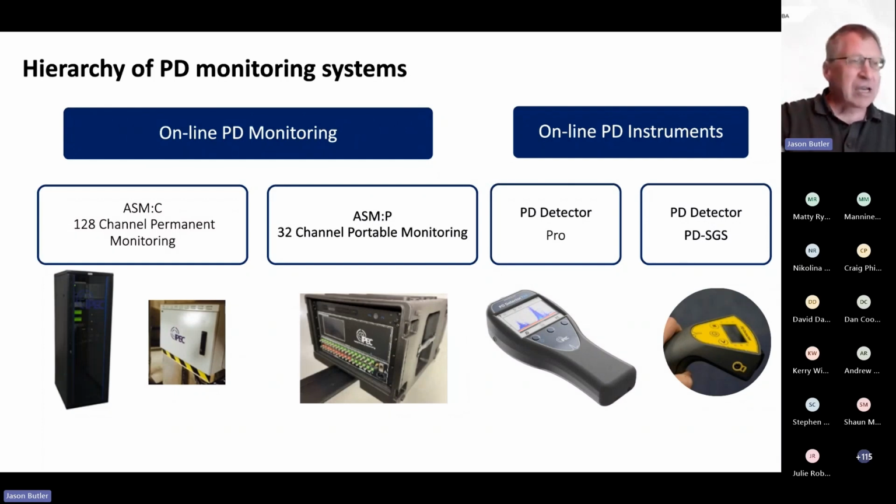Partial discharge has a relationship to humidity. So yes, you should keep your substations dry, but if it's raining, you're going to find more PD than if it's not. So again, potentially on the critical stuff, you look at permanent monitoring.